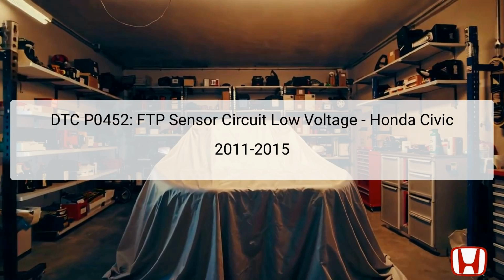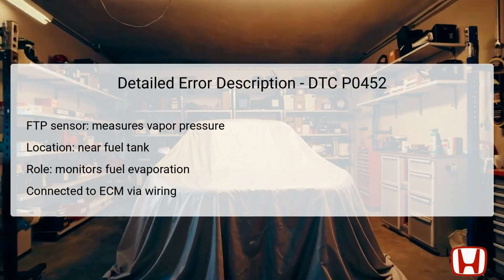In Honda Civics from 2011 to 2015, this sensor is typically located on or near the fuel tank and is connected by wiring to the engine control module, ECM. When this error occurs, it can affect the vehicle's performance and emissions control system, potentially leading to increased emissions and decreased fuel efficiency. The FTP sensor plays a pivotal role in the fuel evaporation monitoring system.